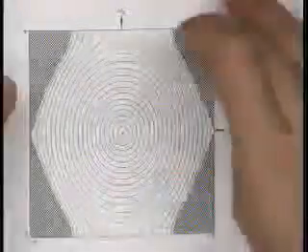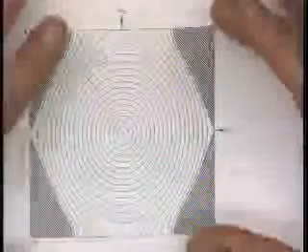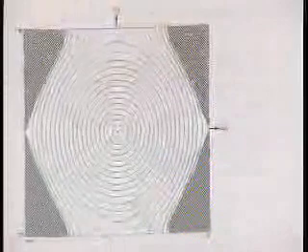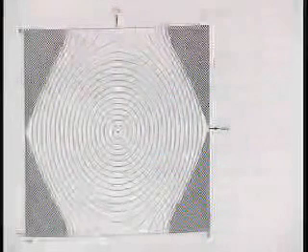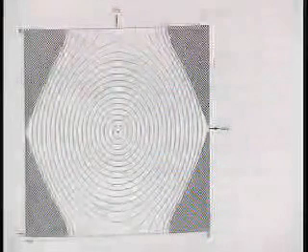And so we want to avoid this. Why did this happen? It happened because the magnitude of T of omega 1 and omega 2 exceeded 1. You're going to ask, did we do anything specifically to prevent that from happening? No. Then it's not surprising that it happened. If you don't actively constrain or enforce some function being in a specific range, it can do whatever it wants. So this T of omega 1 and omega 2 did whatever it wanted.